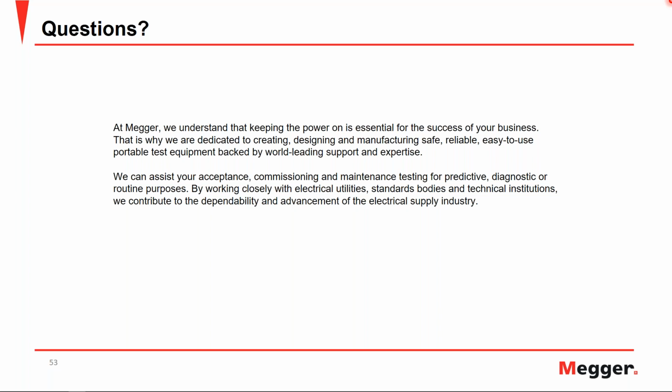Good morning, everyone. That's a very interesting question. The reason I say that is that nowadays you see more and more transformers utilizing natural ester as the insulation medium instead of mineral oil. So this question is very valid. One thing I would like to mention is that natural esters, FR3 or any other, are more polar in nature.